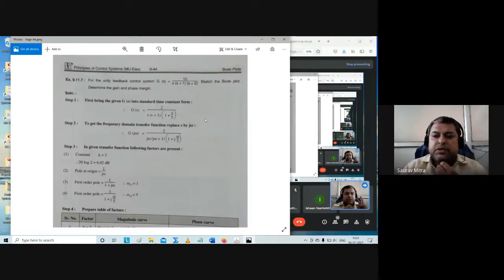Today we are going to see two numericals, and they are very important because in both cases we will be able to see what is gain margin and what is phase margin, because you are seeing that there are three poles in the denominator. Three poles in the denominator means the maximum phase for this Bode plot at omega equal to infinity will go to minus 270 degrees.